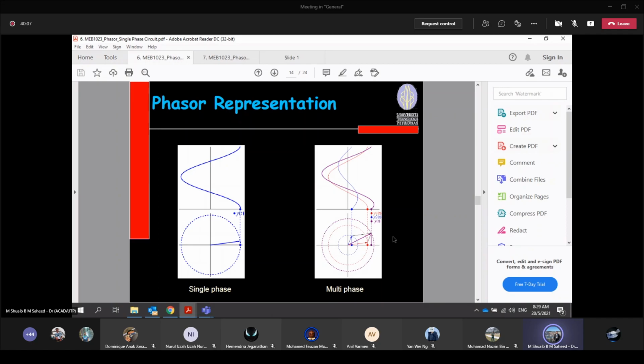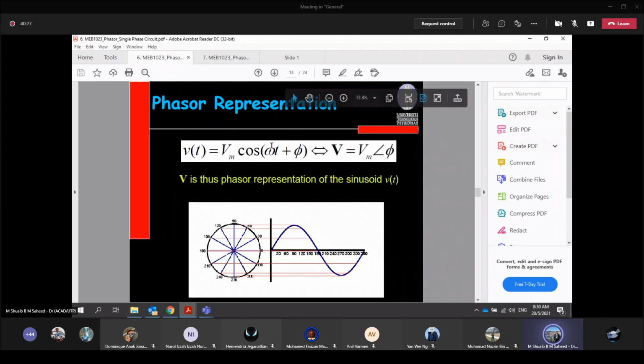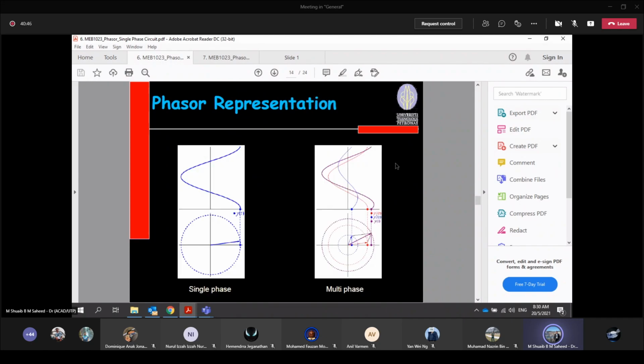You must have the same omega when you are adding, subtracting, multiplying, or dividing two or more sinusoidal waves. Remember that. You can have various phase angles, 5 or even 10 of them, and different phase angles doesn't matter. The only thing that matters is that the omega must be the same for all 5 or 10 waves if you have them. Normally we won't go that far.